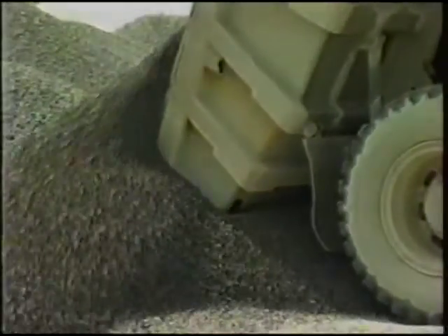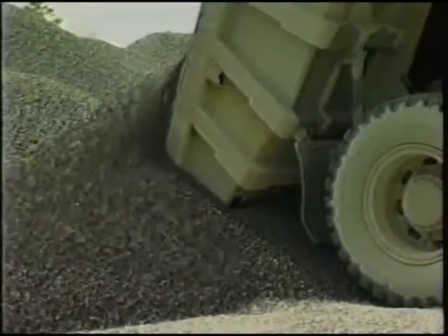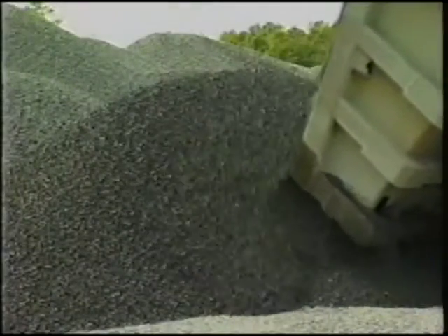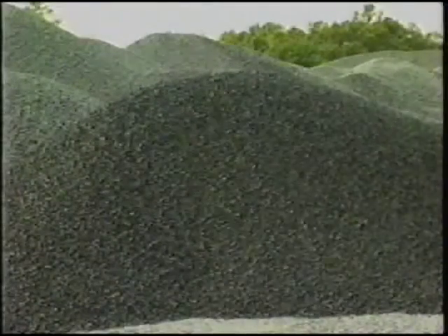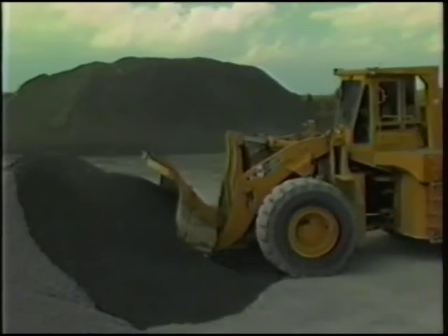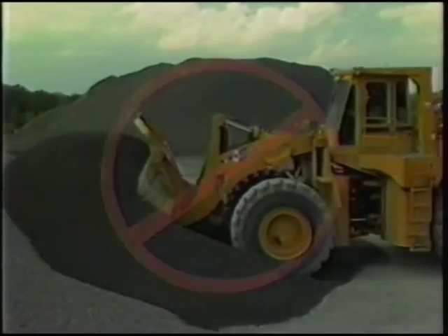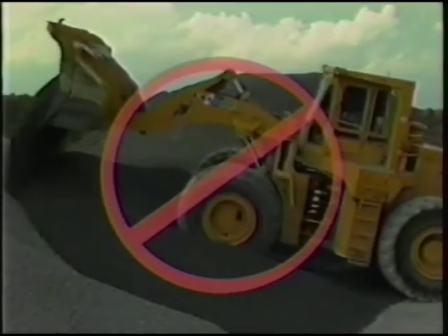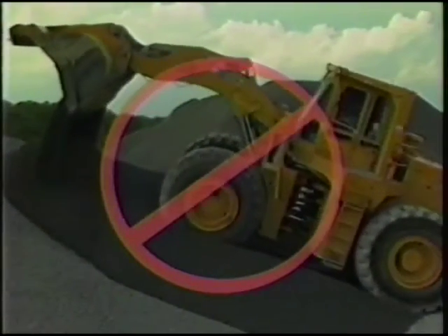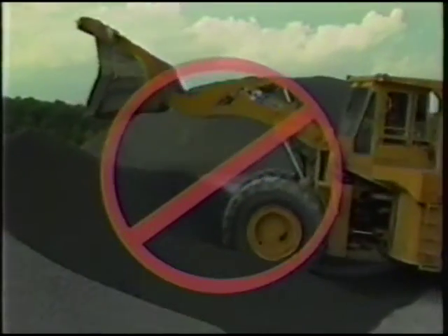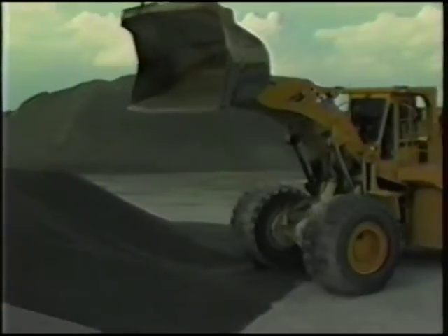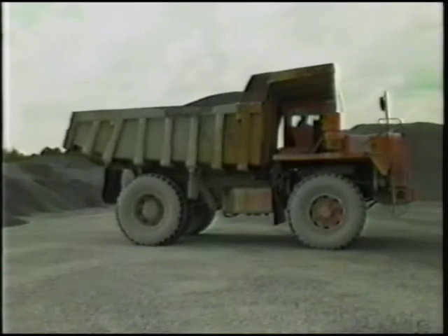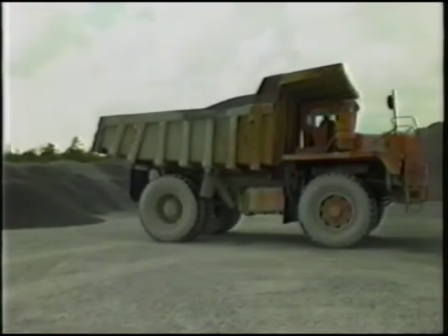Once a suitable location has been prepared, the stockpile is ready to be built. Proper construction is critical to maintaining the gradation of the aggregate product. Poor stockpiling practices can cause crushing of the aggregate pieces. If the gradation is changed either by crushing or segregation during handling, the product may not meet specifications, nor will it have the desired construction properties. Let's look at examples of good and bad techniques for stockpiling aggregate products.